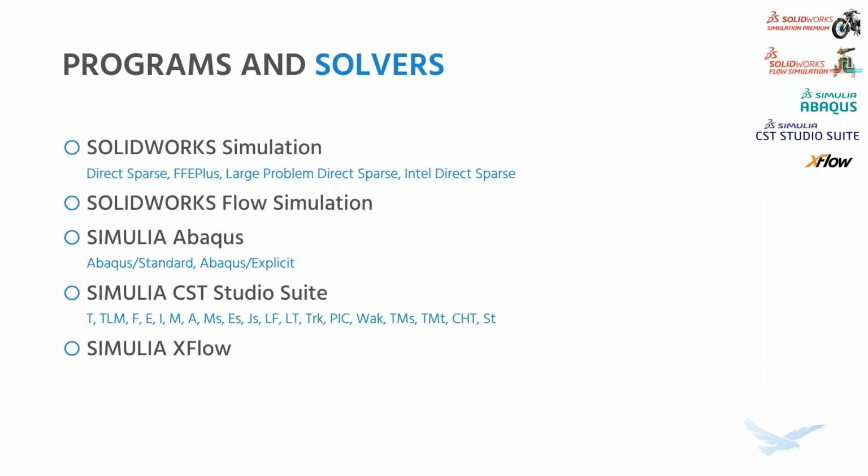Hey, Terrence, what kind of problems would you point XFlow at versus SolidWorks Flow? Yeah, that's a great question. We'll dive in a bit deeper, but as a brief overview, XFlow is really good for highly transient, turbulent flow situations. It uses a technique called lattice Boltzmann. It's a newer technology, and it works really well for those situations. Flow Simulation, on the other hand, uses the old Navier-Stokes set of equations, but it's got a bunch of really good capabilities for solving thermal problems, which XFlow can't do.